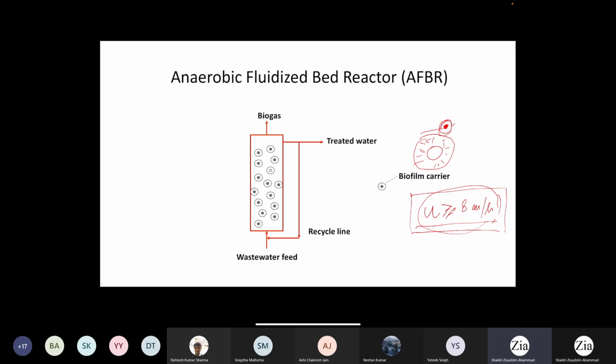So whenever you have higher abrasion, when the granules move inside the reactor, they will come in contact with other granules, and due to abrasion, some biofilm will come off from the inner system, and then the biofilm will go away from the system along with the outflow. Smaller granules will also have the tendency to go out of the reactor. So you will have entrainment loss when we use this fluidized reactor system.